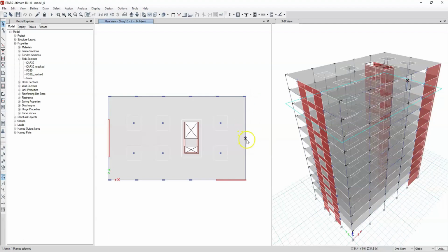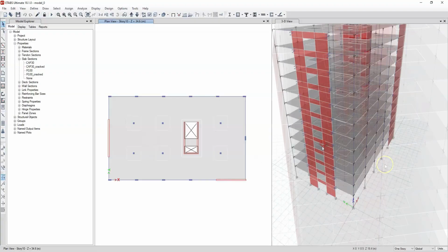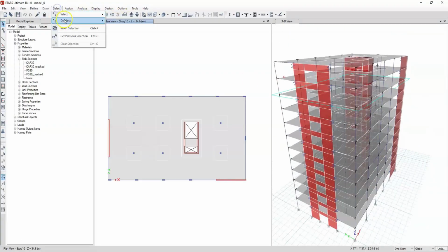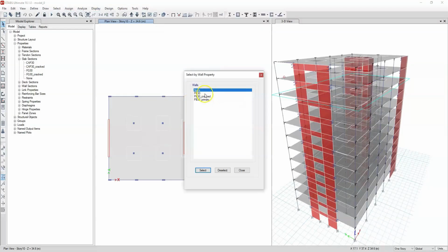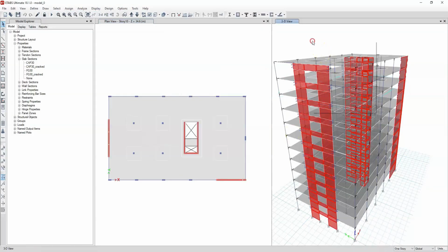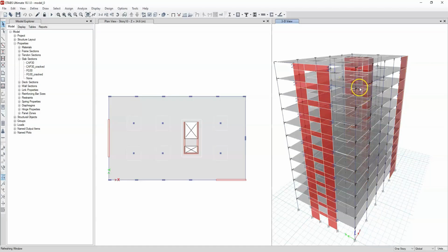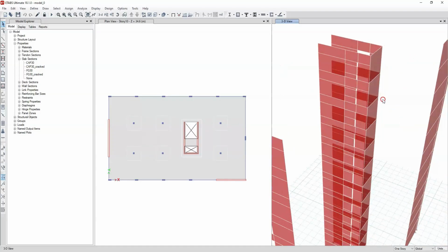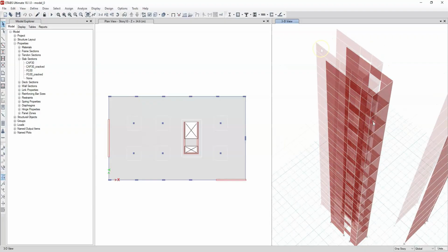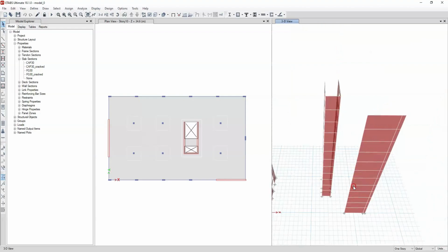As for the walls, we have in our building generally a thickness of 30 centimeters. And we have 3 specific wall zones in our model. In the left zone, 2 walls with a 3-meter length are coupled by beams with a 1.2-meter depth and a 3-meter span. In the central zone, we have a C-shape coupled with 2 walls by beams. And finally, on the right side, we have a wall with a length of 7.4 meters, which makes this structure more asymmetrical.